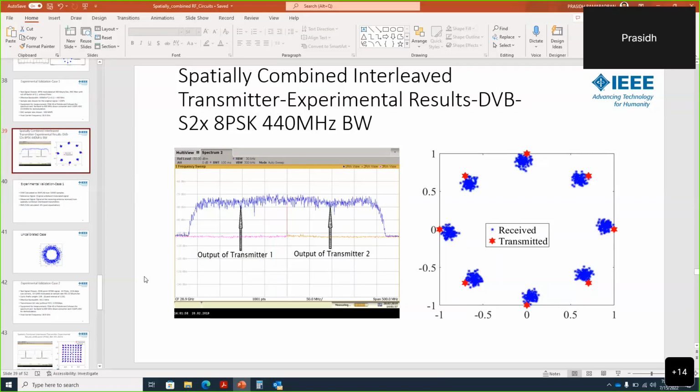The reason is that any clock skew you have here, since you're not using the clock to put out your two signals, the two signals that you get may have skews, but they are independent of the mux here. So any skew here is going to manifest in the form of a phase shift. Do you agree? Yep. So that phase shift can be corrected by coordinate rotation of each path relative to the other.